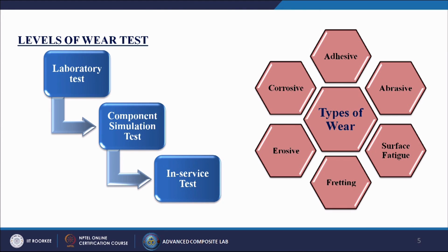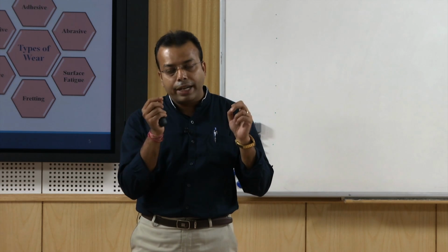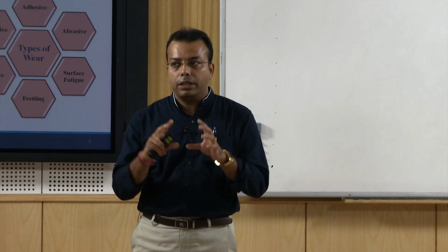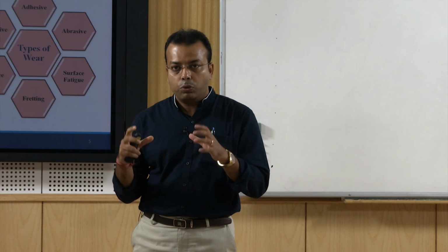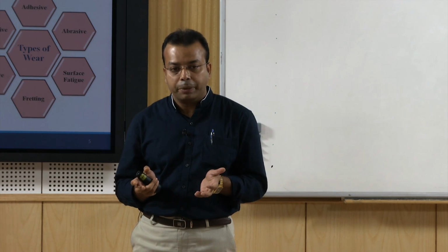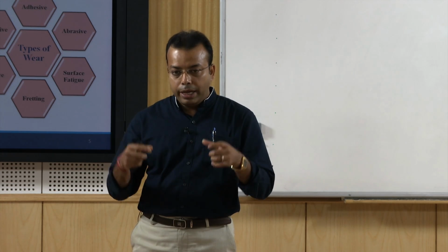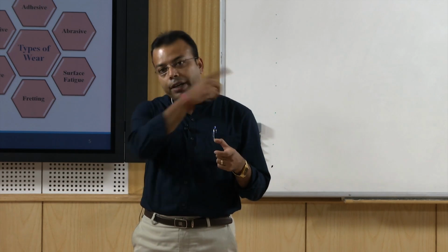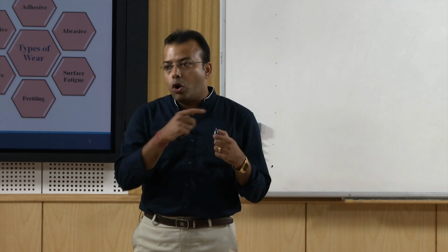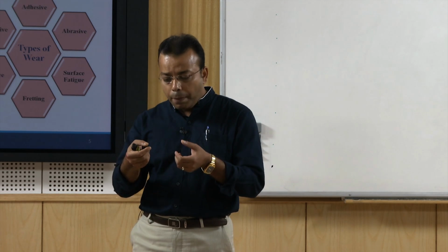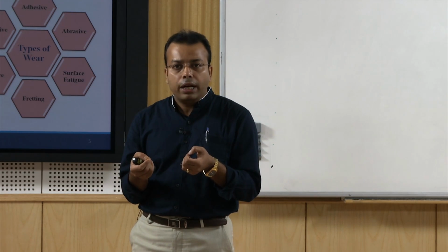Second is called the component simulation test. So, when we are designing some kind of materials by AutoCAD or some kind of CAM design, first initially we are drawing the material, designing the material, what will be the depth, what will be the size, what will be the effect, everything. So, after certain time, if we check whether that material is having exactly the same shapes we have given earlier at the time of manufacturing, we can measure whether any wear takes place or not by simply deducting both the values.